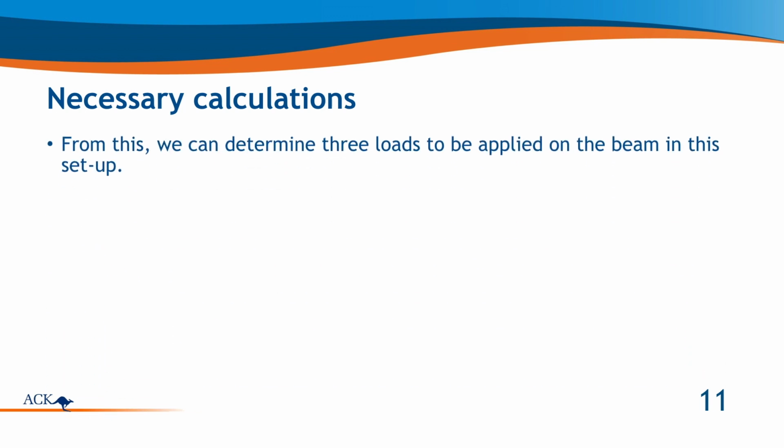Now from this, we can determine 3 loads that we can apply on the beam, just like I mentioned earlier. And then once we apply the loads, we can measure the deflection, we can plug them into the equation for the deflection, and then solve backwards for E.